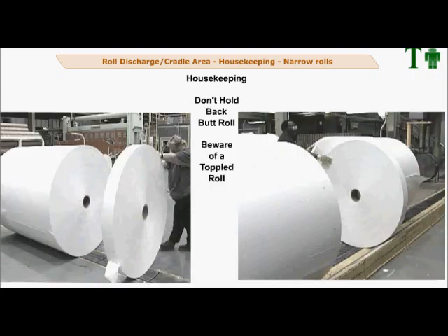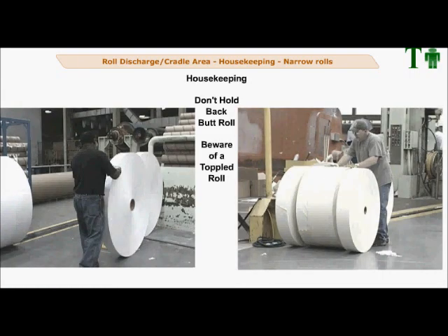The chance of a narrow width roll tipping over must be minimized. Not only is it a concern of the roll falling onto a body, but dealing with it afterwards. These narrow width rolls can weigh 500 pounds or more, and picking them back off their sides can be a safety concern that can cause back strain or the danger of it toppling back over.